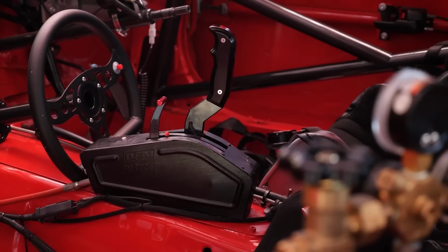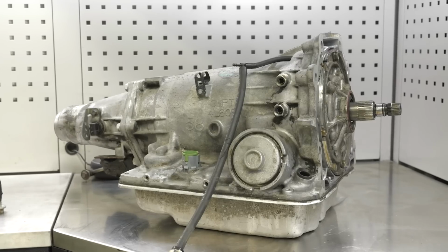Before we move on to the rest of the system, let's quickly recap what we've learned in this module. The valve body is a critical assembly in automatic transmissions, consisting of fluid passages, solenoids, valves, accumulators, and electronics. Its main job is to deliver fluid at varying pressures to different components. Pressure control and transitions are managed through systems like oil accumulators, which dampen pressure increases, though more modern transmissions utilize pulse width modulated solenoids, which precisely control fluid for optimized pressure curves and can help with fault finding as well as tuning.